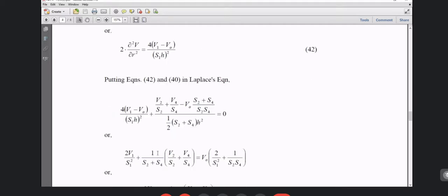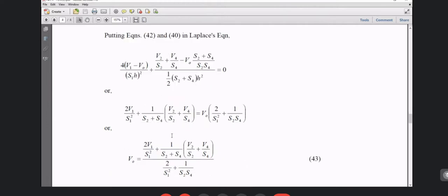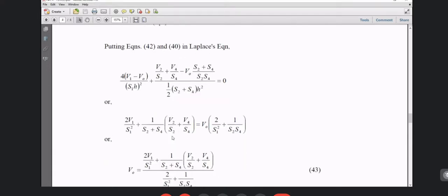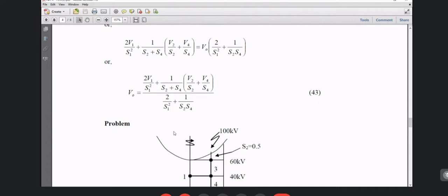Similarly, you write down the Taylor series for node 2, 0, and 4 and get an expression for the del 2 v del z square. And then you put everything together and simplify the whole thing. You get equation 43, which is the FDM equation for axisymmetric system with unequal nodal distance, and when the node 0 is lying on the axis of symmetry.